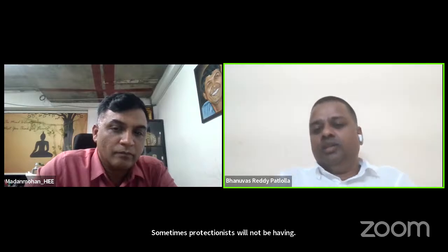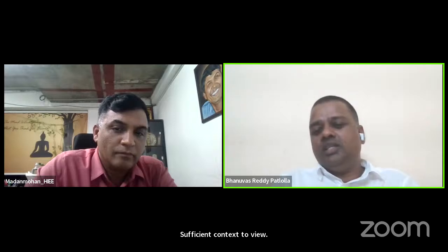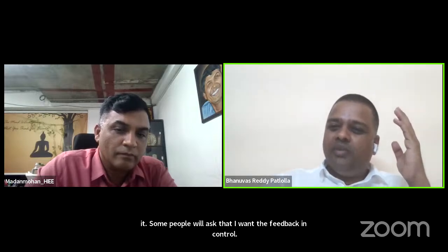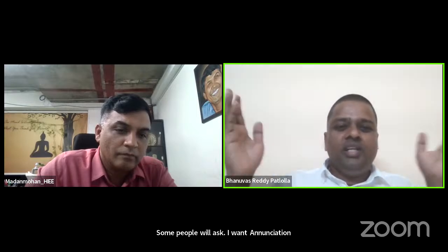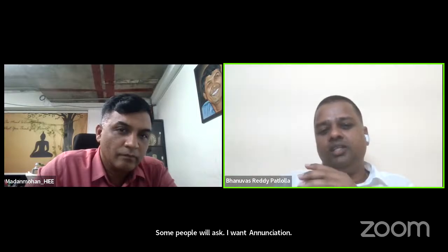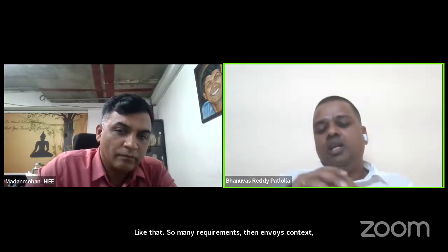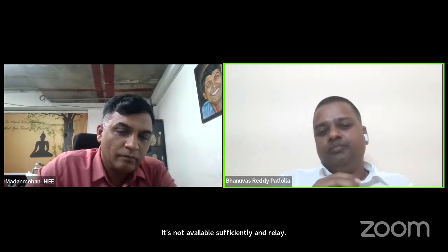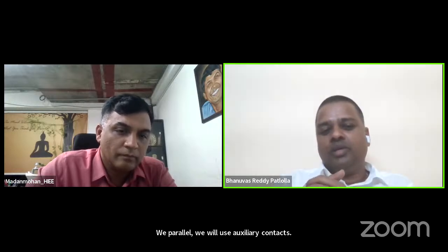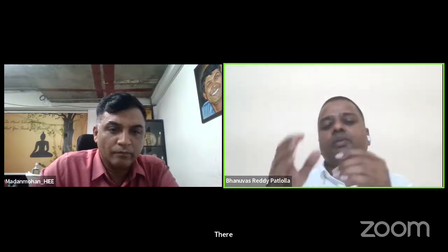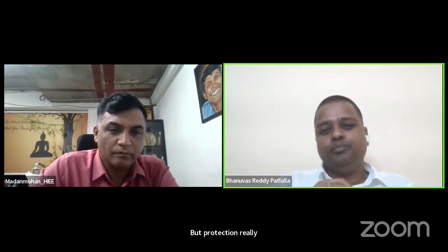Some people will ask, I want feedback in the control room. Some people will ask, I want annunciation. Like that, there are so many requirements. Then NO/NC auxiliary contacts are not available sufficiently in the relay. In parallel we will use auxiliary relays, multiplication contacts, contactors, and we can set a multiplication relay like that. Auxiliary relays are common. Any relay can use an auxiliary relay, but protection relays are specific for protections.